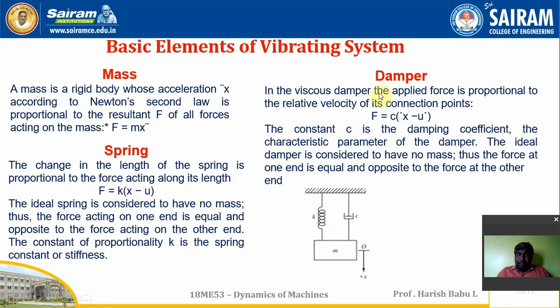When you go for the damper, normally viscous dampers are considered for vibration analysis, because that is very simple. The differential equation will be very simple for calculation. That's why normally you consider viscous damping as the example. In viscous damping, the applied force is proportional to the relative velocity of its connection points. So the damping force will be given by F is equal to c x dot.